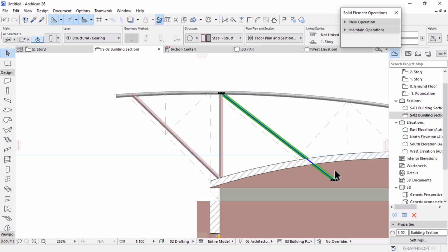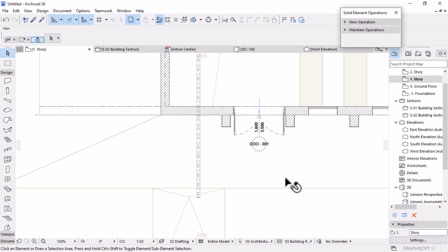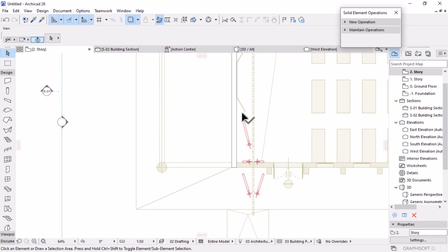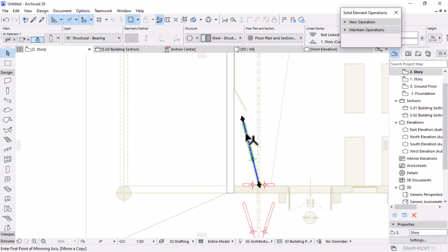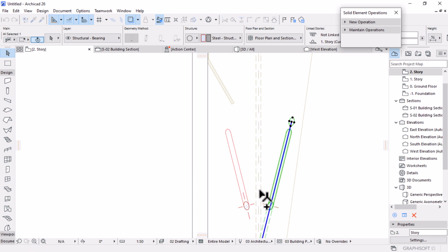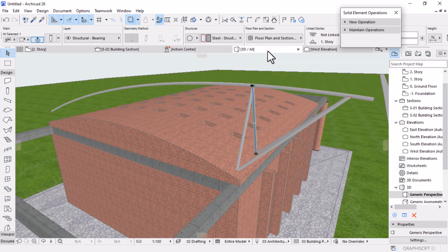I'm not going to follow the sketch, but as long as it's in the range, guys, for the sake of this demonstration. And then let's go back to the plan view. Pick this one, Control Shift M, or I could finish the entire length and then do copies once I'm done.